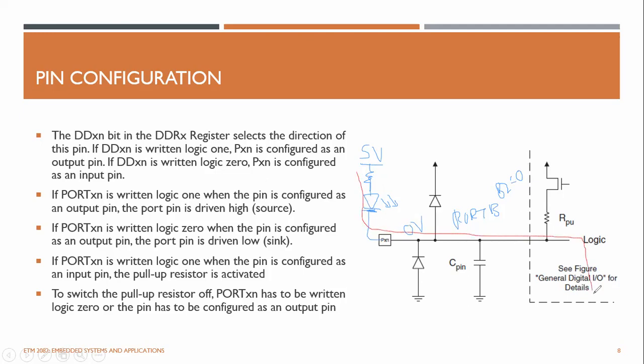through this port to the ground. So this LED will light up. So it is sinking the current in this direction. In the previous case, it was sourcing the current, and now it is sinking the current. So both configurations are possible, sinking and sourcing the current, depending on the way that you connect your output devices.